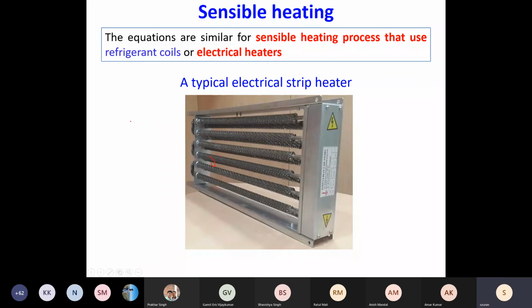When you go to the dry mode, instead of following, let's say from here, this process line, it will cool further so that you dehumidify further. That's all it does. In fact, you will feel very cold if you use that dry mode in your AC because it only has a cooling coil. So all it can do is cool and dehumidify. It cannot attain only dehumidification.